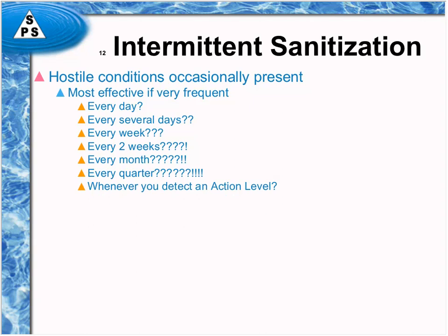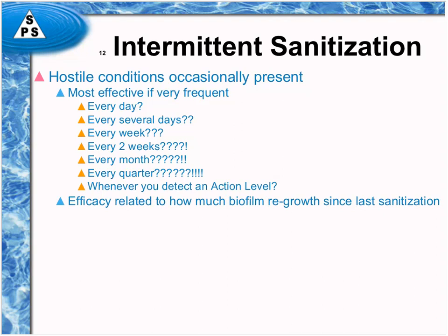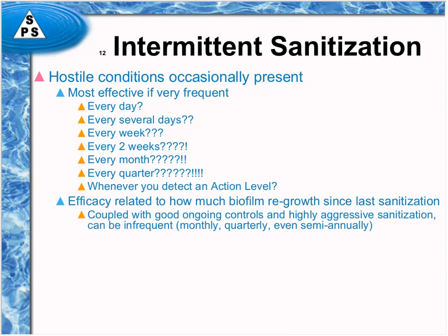I've even seen folks that do it every quarter, and some folks, very commonly, do their sanitization only when they see an action level of microorganisms. And what we'll discuss a little bit is that's exactly the wrong thing to do. But efficacy is related to how much biofilm regrowth has occurred since the last sanitization.